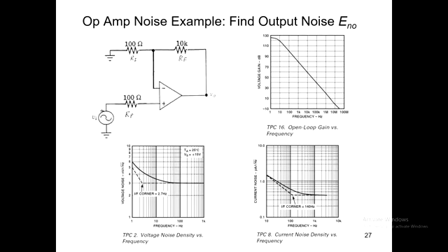Right, so the noise bandwidth will be a little bit more than that, yeah? It's first order roll off, therefore we're happy to use pi on 2 for the fudge factor, the correction factor.